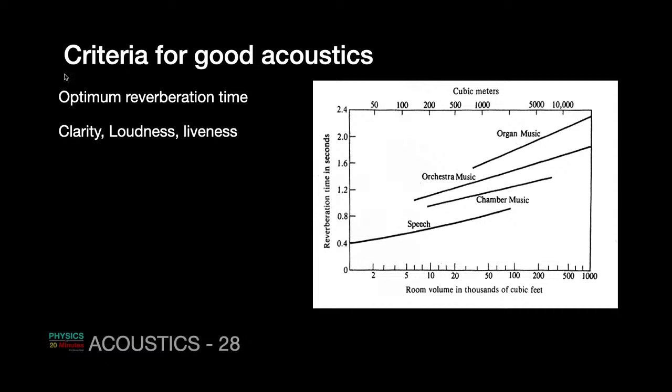So the idea is that there should be an optimum reverberation time. Too little reverberation time means the speech, audio, whatever, is too dry to perceive, to experience. Too long a reverberation time, again, the sound will get mixed and muddled up. So there has to be an optimum reverberation time.